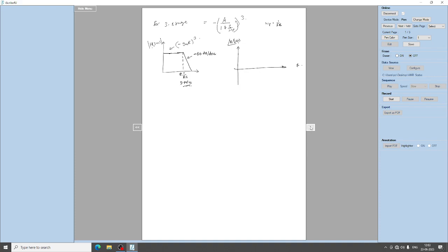So you have a DC gain of minus 180 degree. So at minus one, at 180 degree, the output is out of phase. So at 180 degree you have a 3-stage RC. 3-stage RC can produce 90 plus 90 plus 90. So this is minus 90, this is 90, and this is 2 90s.